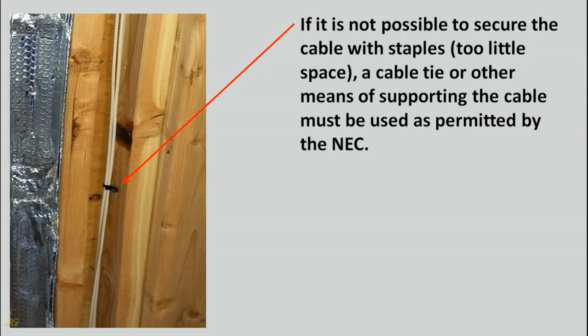If it is not possible to secure the cable with staples, for example too little space, a cable tie or other means of supporting the cable must be used as permitted by the NEC.